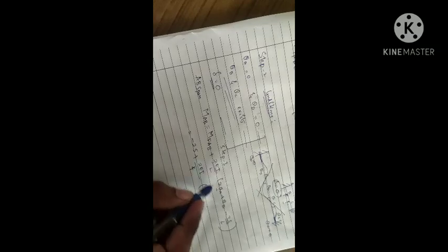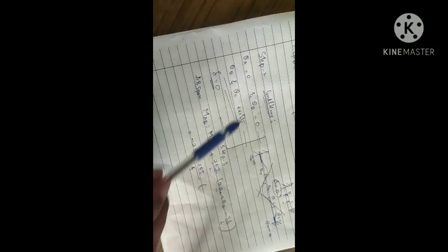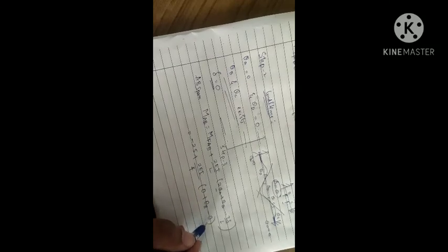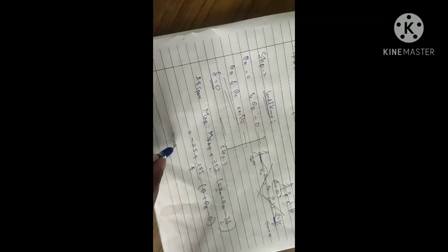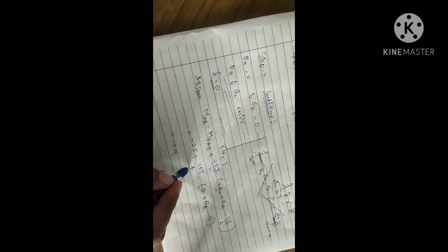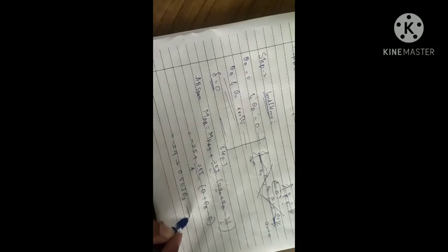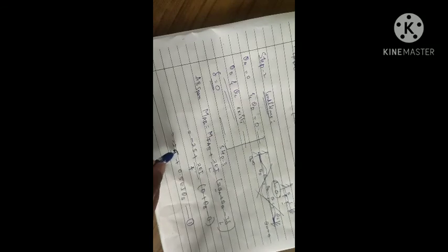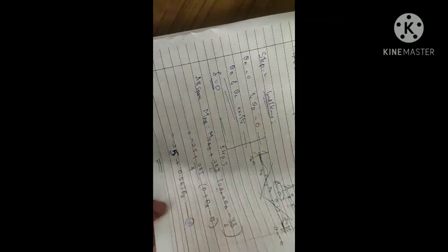So theta A, here you should see what the conditions are. Theta A is equal to 0. Theta B exists. Delta is 0. So minus 25, 2 1s are 2, 2 2s are 4, 1 by 2 is 0.5, half. So EI multiplied by theta B, so this will be 0.5 EI theta B. Rest all is 0. So minus 25, this is not 24, this is 25. This is your equation 1. Similarly, you need to make the other 5 equations.